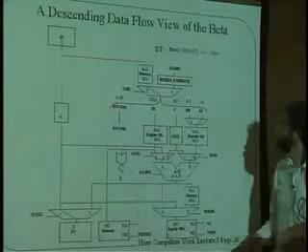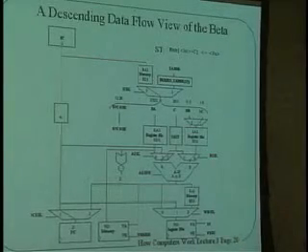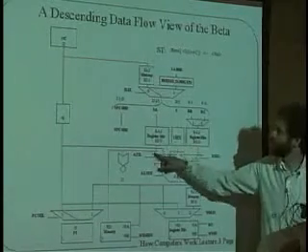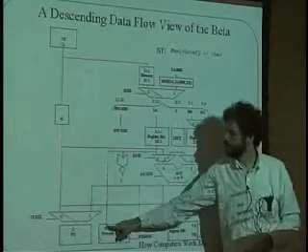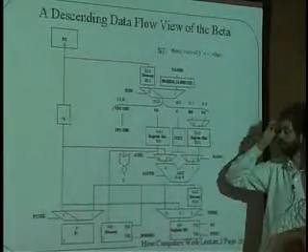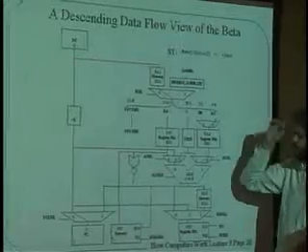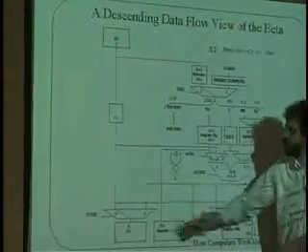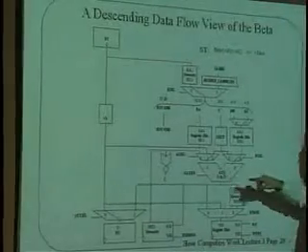The data that pops out of the ALU is going to go to the memory system. Now, what data are we actually going to put in there? The contents of register A. That comes right over here and goes straight down into here. No computation at all is being done on the contents of register A. However, the address in the big slow memory that we're going to write the contents of register A is going to come from the ALU.